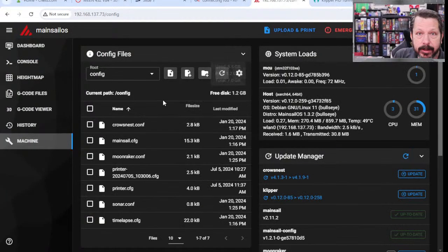The idea here on linear advance or pressure advance is that when you get to a corner or a new line, if you were able to predict the amount of oozing that's going to happen. So I just printed one layer and I'm going to move up and print a new layer, or I'm going around a corner so I just changed speeds. If I'm able to predict the change in speed, I can stop extruding filament a little bit early and rely on the ooze that's going to happen because there's a lag.